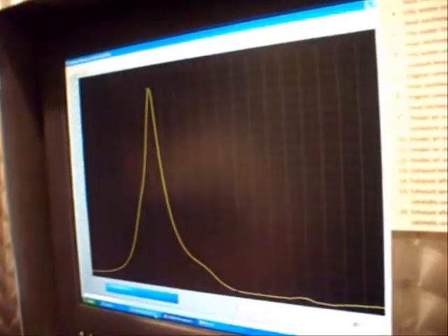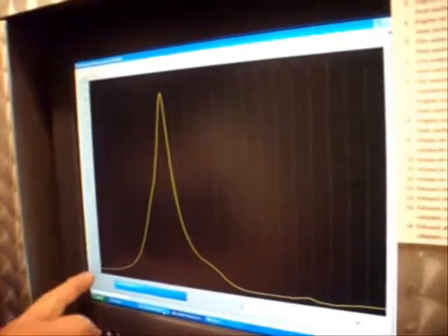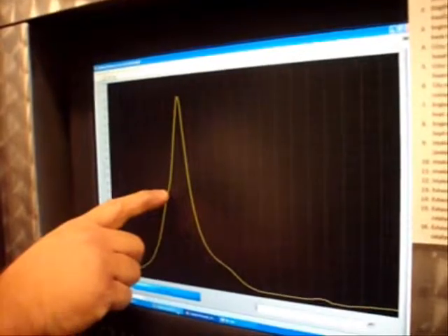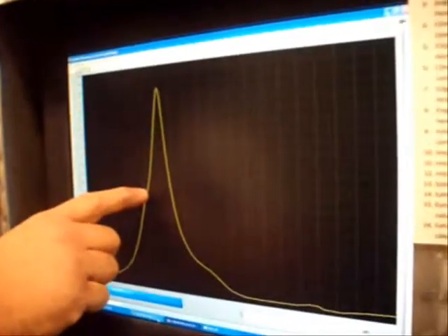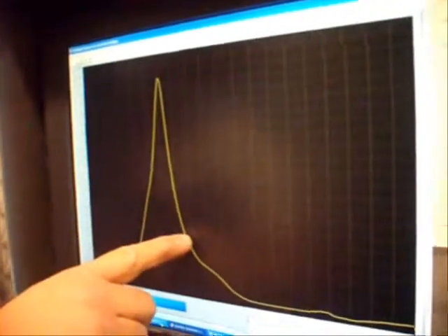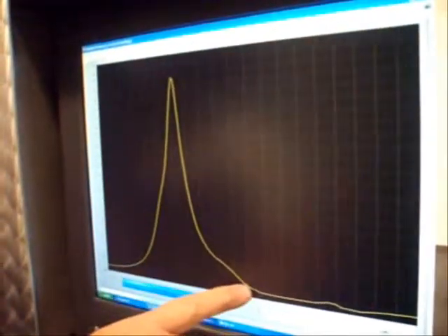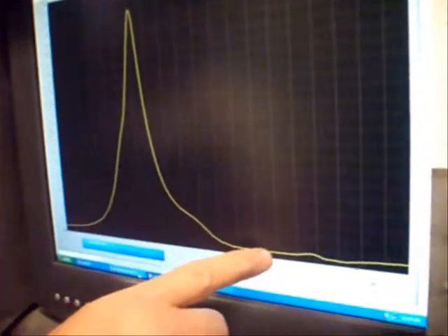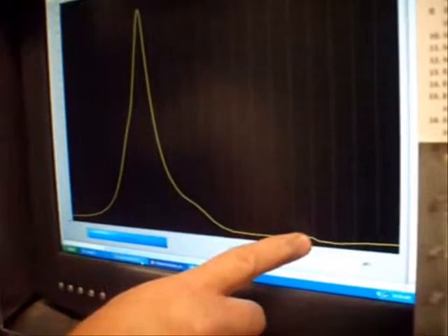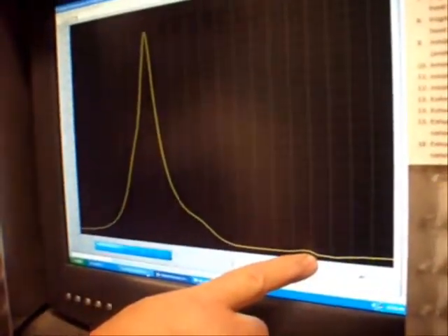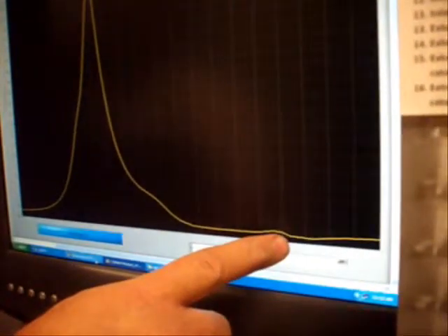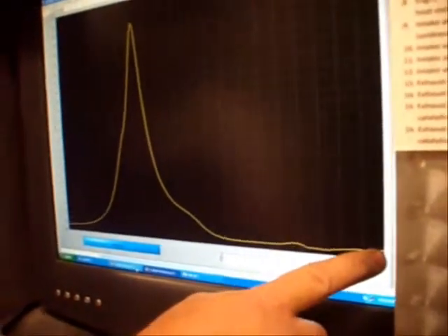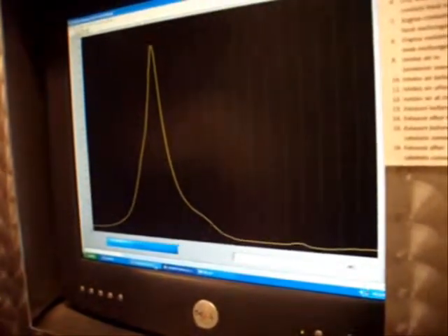So looking at this trace, I'll briefly describe what each process is. We're going to start at bottom dead center, and this is our compression cycle. Right about here we reach top dead center, and our combustion process occurs. That's where the work is actually done on the piston. Now we reach bottom dead center again, and the exhaust valve opens. The piston goes up, pushing out the exhaust, and then right here at this drop, at top dead center, we close the exhaust valve and open the intake valve, and we draw in the air and fuel, and the entire process restarts.